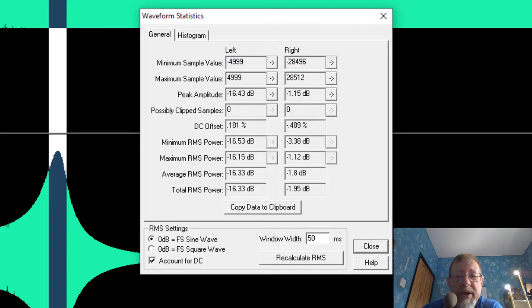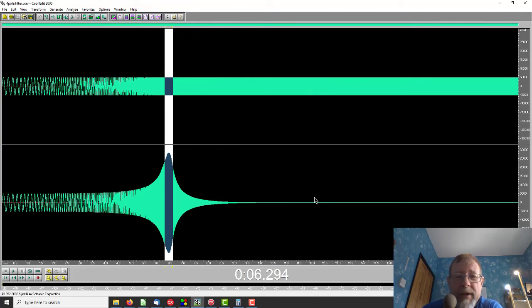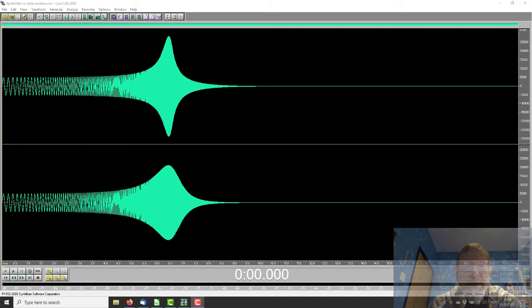However, there are issues with doing the filter this way due to the lag down the filter, so we're not surprised that it doesn't behave exactly how we would expect. And just out of curiosity, how does it compare to our state variable type filter? Well, here we have the 4-pole filter at the top and the old state variable type filter at the bottom, and you can see the 4-pole filter seems to give a sharper resonant peak, but apart from that, pretty similar.